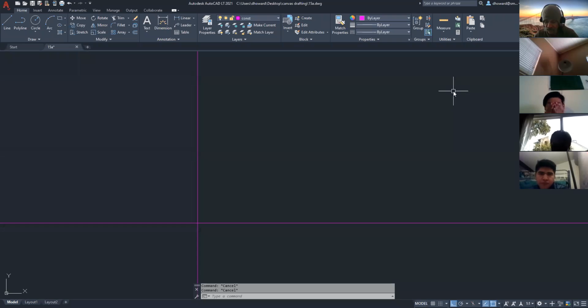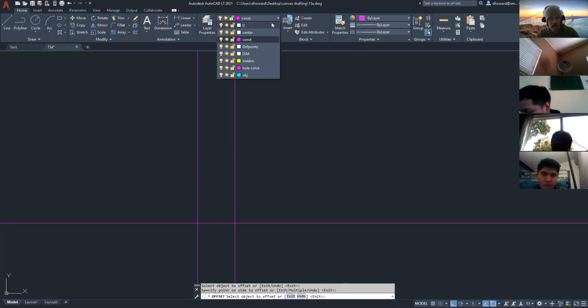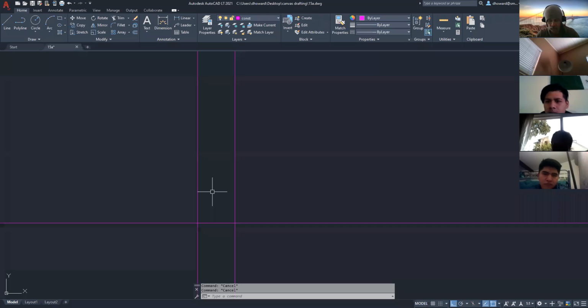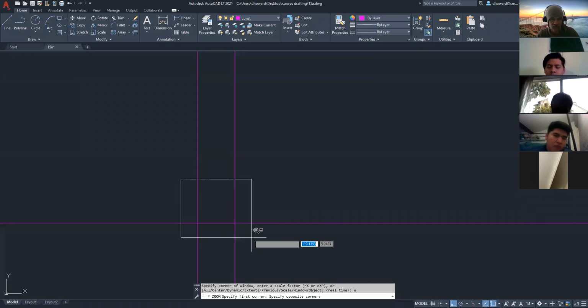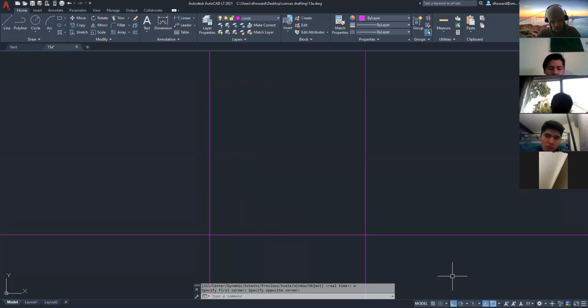So I'm going to do my first offset of 3.19. There it is. I can see that I'm going to need to zoom in on that a little bit. So we'll make that more of my screen here. Something like this. All right. And now I'll start offsetting the various features. I see from this lower corner, I can offset 1.56. So I'll do that.